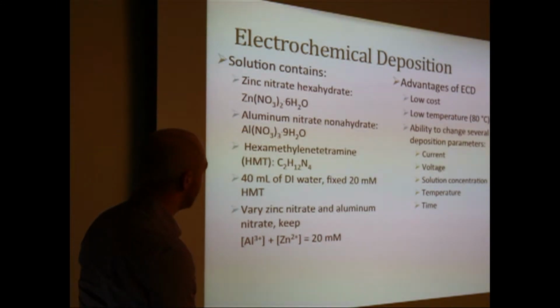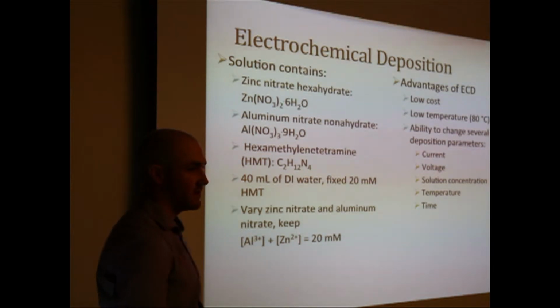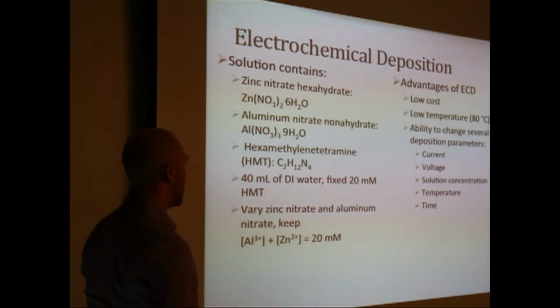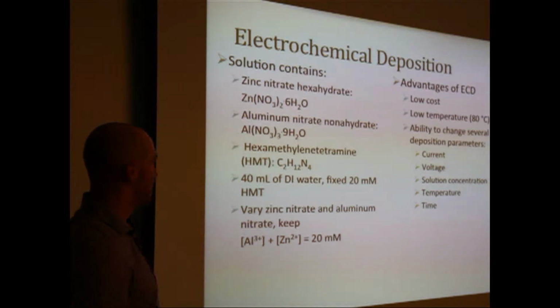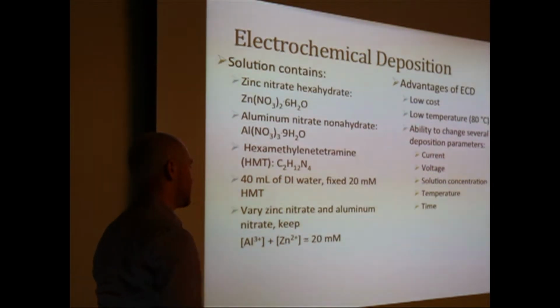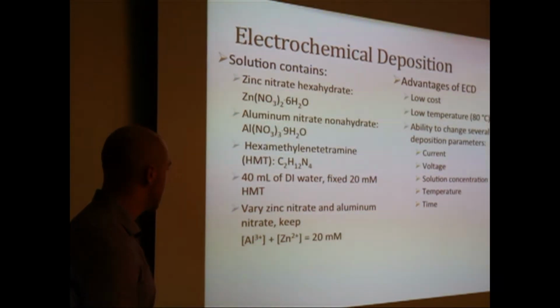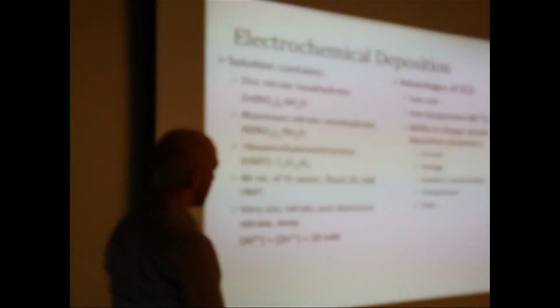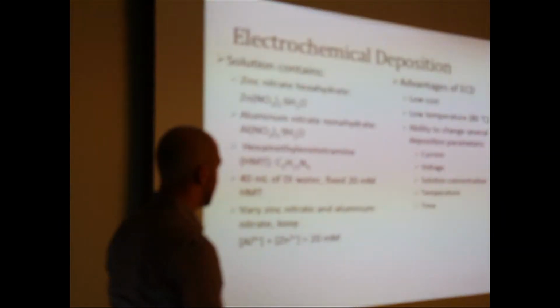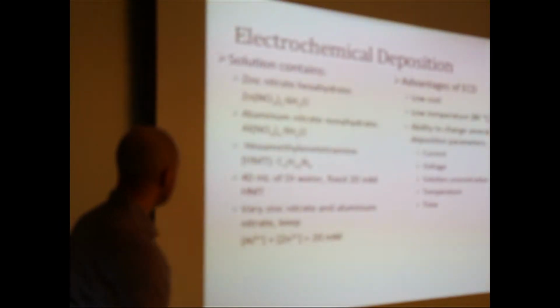The advantages of this electrochemical deposition method is that it's low cost, very low temperature, and we have the ability to change several parameters such as the current, the voltage, the solution concentration, temperature, and time. For our case, we're only changing solution concentration and keeping everything else the same.